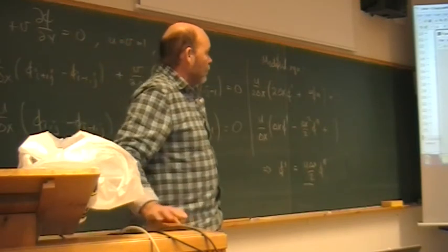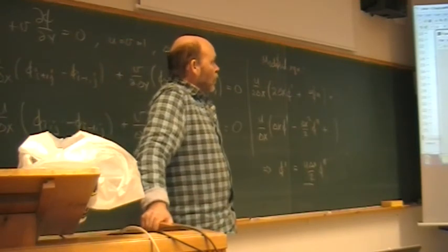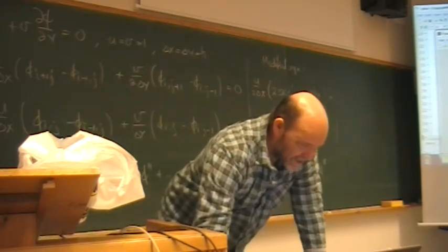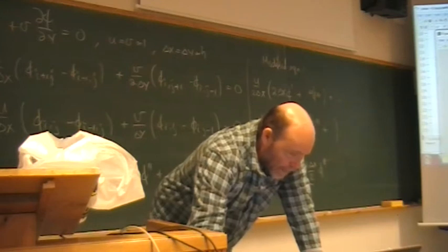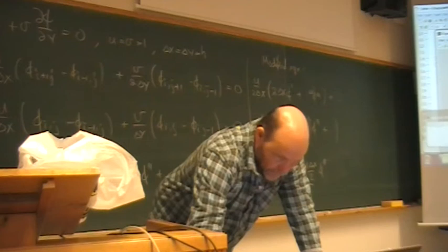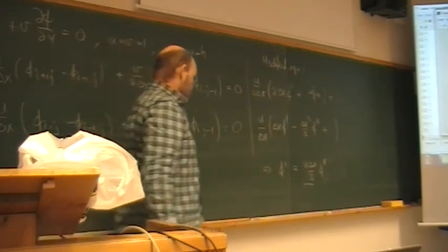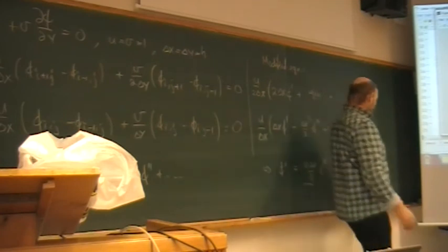So the trouble now, having a flow at a 45-degree angle on the mesh, it's not fun using upwind scheme. Much more fun using central scheme if you can do it. So that's the problem. Of course, you have more advanced methods with this upwind concept.